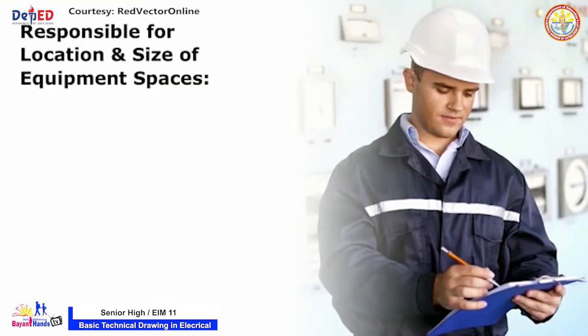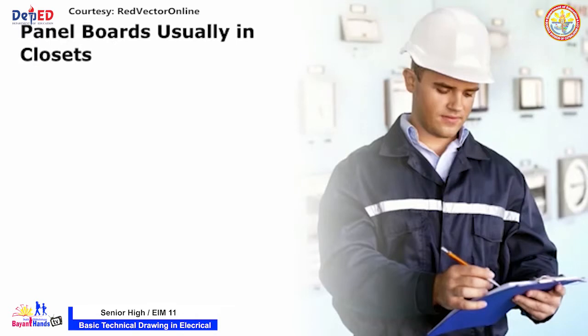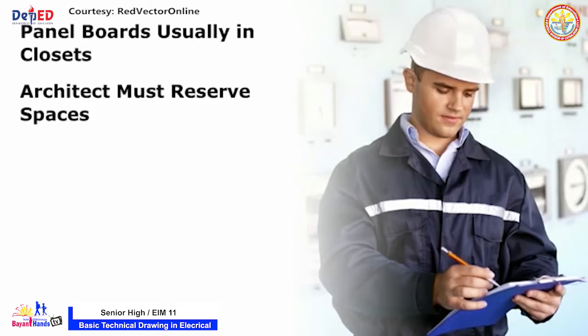The electrical engineer is responsible for determining the location and estimated size of all required electrical equipment spaces, including switchboard rooms, emergency equipment spaces, and electrical closets. Panel boards are usually located in closets, but may be in corridor walls or other locations. The architect must reserve spaces for electrical equipment.